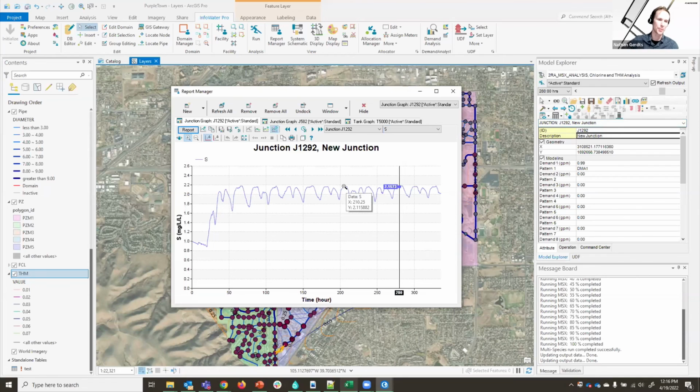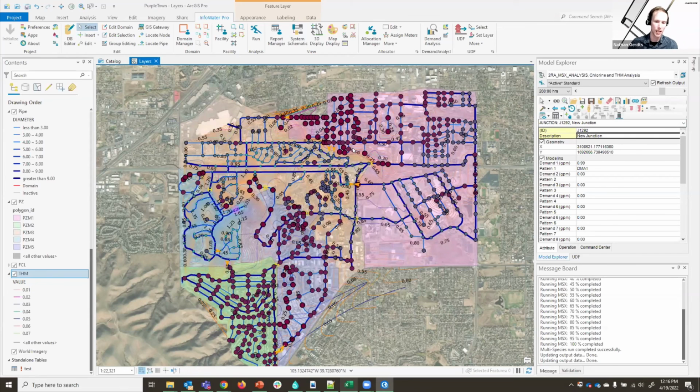And then the S is what helps you calibrate that tail slope. So they each have a unique role in the equations. And it's really more of a spectrum of different reactants in the water quality. And they also influence each other. So the chlorine is dependent on both the fast and slow decay, but then the slow reactant is also influenced by the chlorine. So they're interacting with each other in multiple different ways and feeding off of each other depending on how quickly they're decaying or not. Yeah, that's a good point.